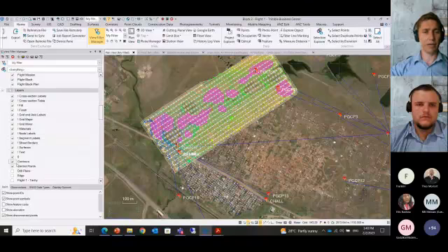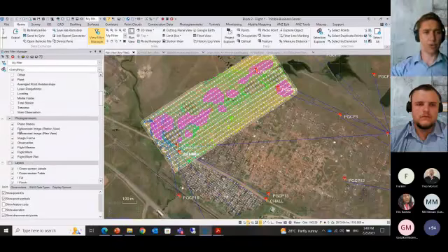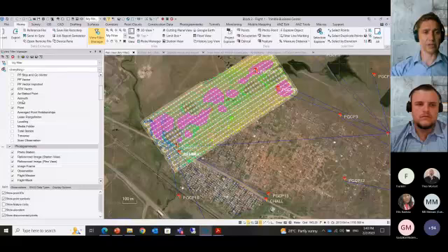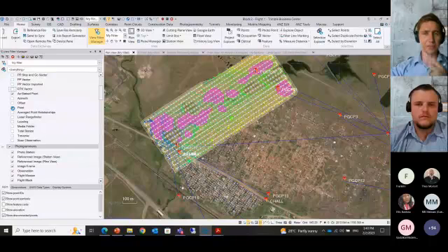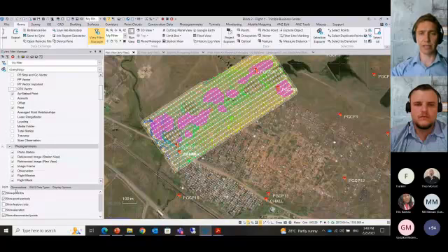For now, I am going to switch off my raw data, which is my RTK vector data, and I'm also going to switch off my points. You can assign these to specific layers, and as you can see, that is now hidden. I'm going to switch off my point IDs as well.